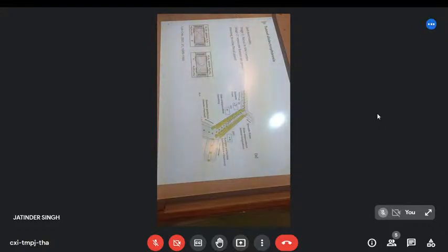And then we come up with kind of a leaf blower where some of the particles get a very big push and they migrate quickly toward the other electrodes. The other particles don't experience the same force, and therefore, by positioning our outlets, we can get them separated into two different fractions. Dielectrophoresis using an AC asymmetric field, so that we've got different nodes where, depending on the size and the dielectric permittivity of the particles, they will concentrate, focus in one zone or another.